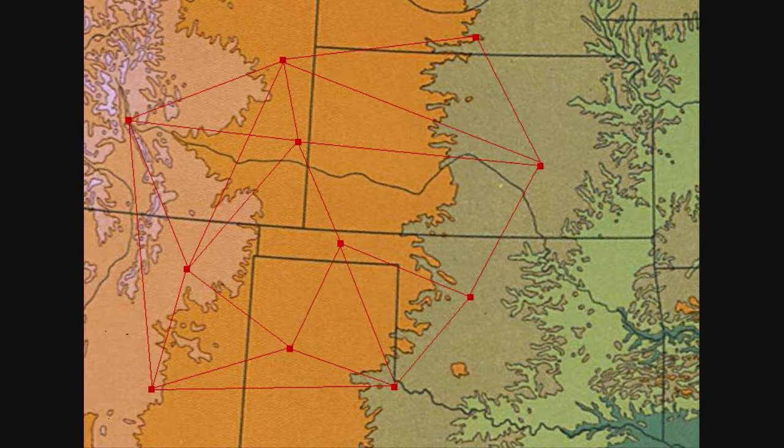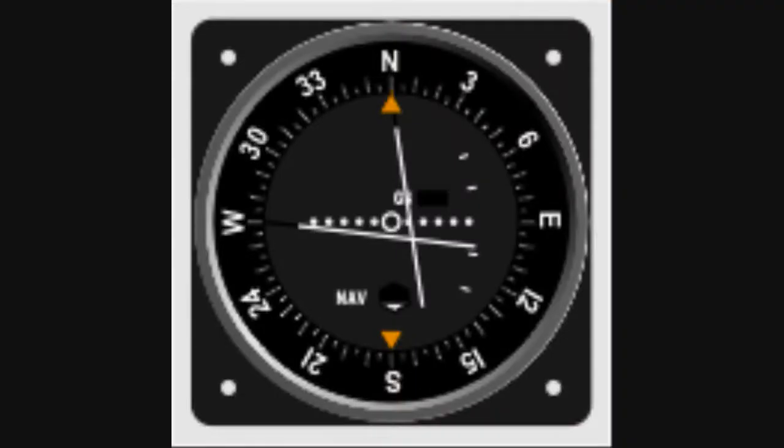Alright everyone, now we're going to move on to something fun, and I guarantee you're going to use this. Now, if you watched my previous video, you may have seen this gauge working. This is the VOR 1 gauge. This is exactly the same as the other gauge, except it has a little feature that I love, called the glide slope indicator. The other gauge does not have it. It is that horizontal bar that you see.